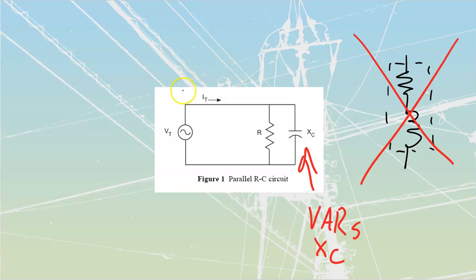Once again, as this is going to be a parallel circuit, our constant for the circuit is going to be voltage. That voltage is going to equal this voltage, which is going to equal this voltage that we will have across each one of these. And we're going to use a lot of the E squared over top of our formula to convert everything into power. Once again, because power is going to be our friendliest value to work with. Power does not lie, so let's work with it where we can.